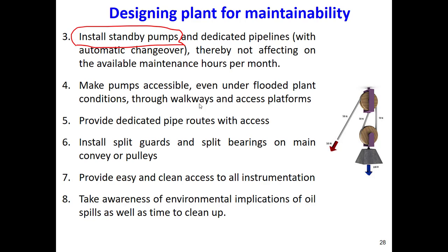Most of the time for the pumps we also install one parallel pump or one parallel compressor, so when the pump needs maintenance we switch to the parallel pump, we do the maintenance, we fix it, and then we switch back to the main pump. So we need to design such things in the process.